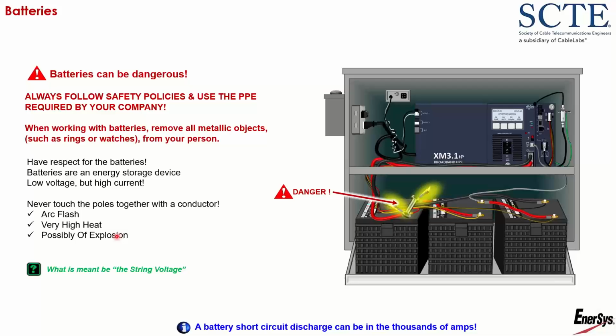It's possible even for the battery to explode. Question I have here, what is meant by string voltage? Well, string voltage is the total voltage of the string. In this case, my string is 3 batteries connected together. So I can check string voltage in 2 different locations.